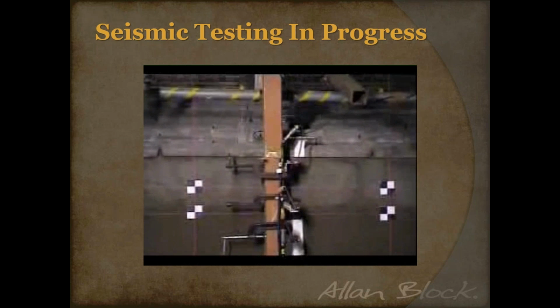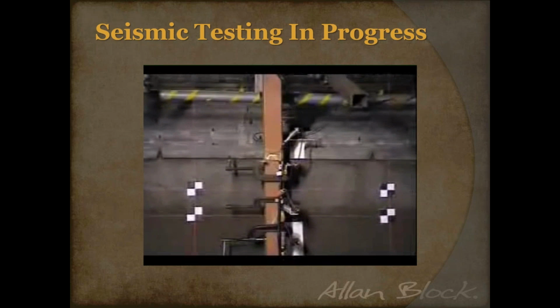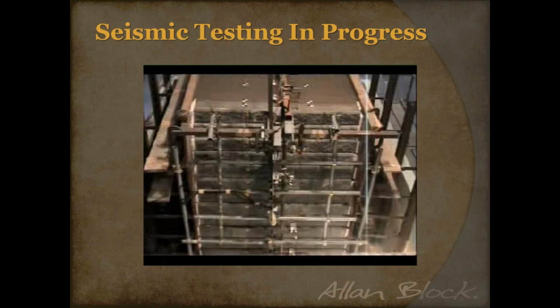This is of our structure number 3, a top-down view. Right now I'm looking at the top of the block, going down the front of the wall. You can see the string lines overlaid over target discs that are on the soil itself. The string lines are connected to the frame.